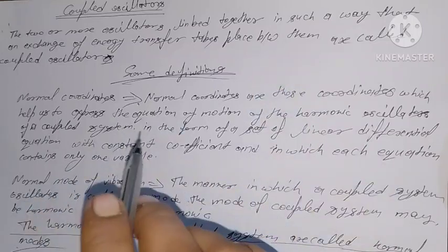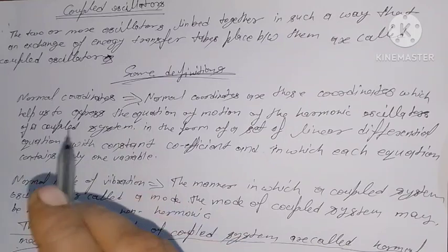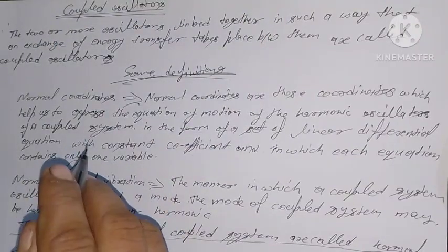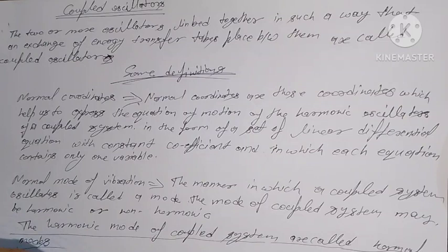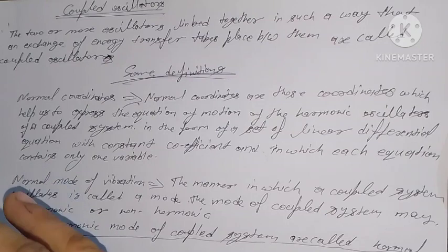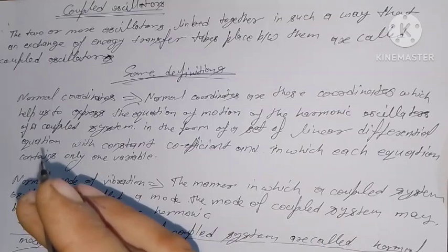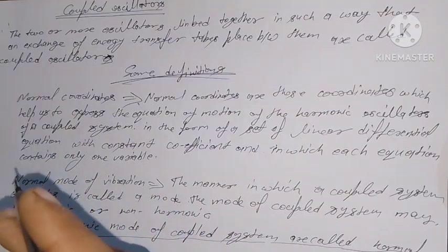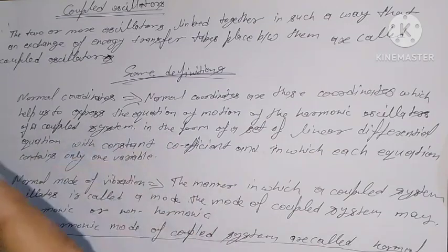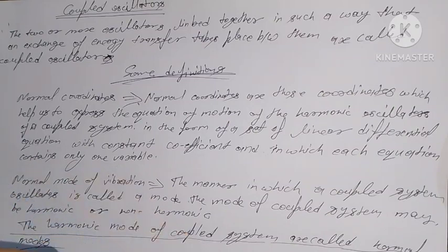The normal modes of vibration are entirely independent of each other, since the energy associated with a normal mode is never exchanged with the energy associated with another normal mode. The total energy of the oscillator is equal to the sum of the energies of all the normal modes. If at any time only one mode is excited and vibrates, the other modes will always be at rest and unexcited, and these will acquire no energy from the vibrating mode.